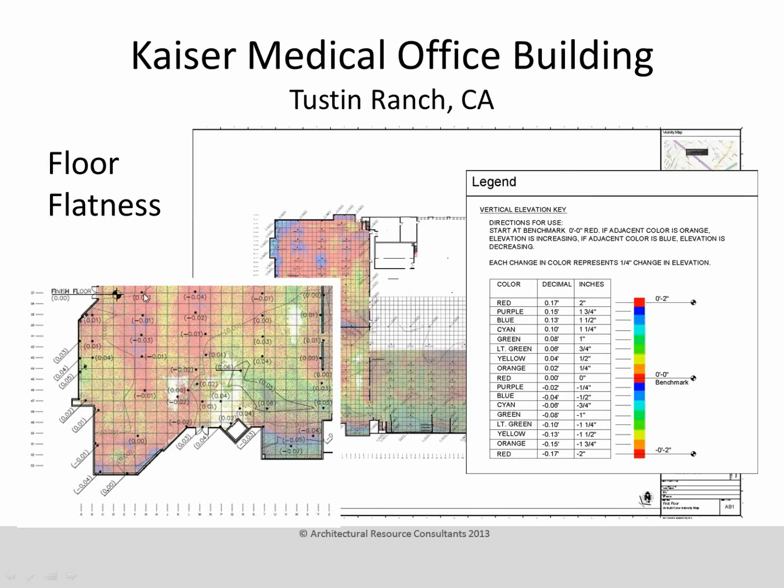So if you were going just with the points that the traditional survey captured, you wouldn't necessarily have a full picture of what the slab looked like. You'd think it was actually pretty flat. So the scan fills in a lot of the detail in between traditional survey points, and you can get a much clearer picture.